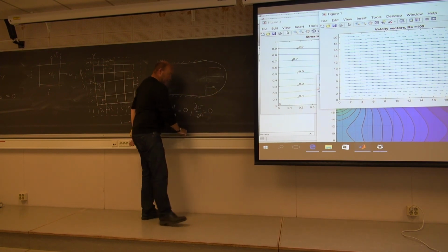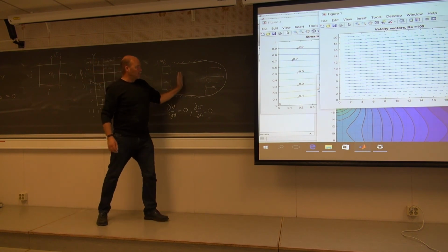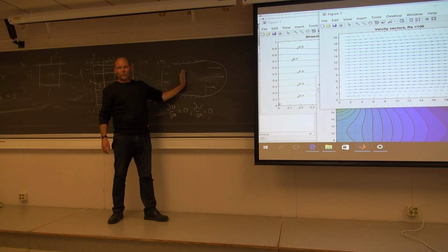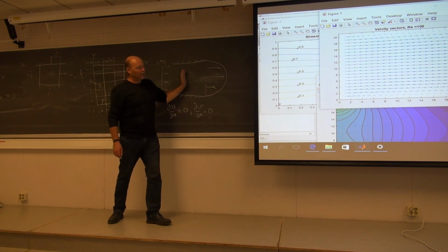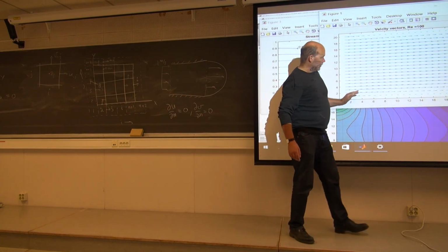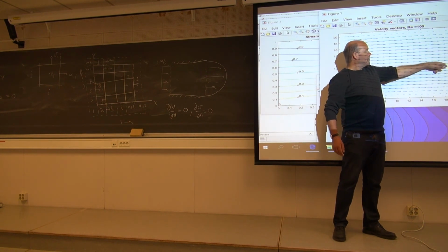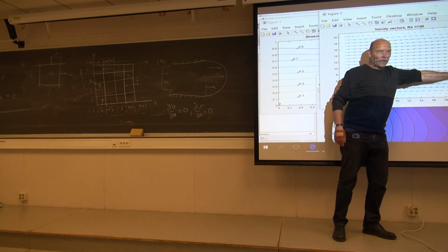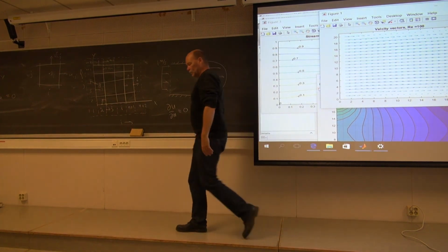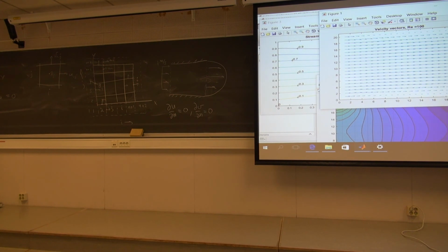And that means if you wanted this one to be fully developed, then you need a quite low Reynolds number. 100 is way too big. So it's not finished, it's not fully developed. You'll have a boundary layer growing here, but the boundary layer should grow so that they meet in the center before the outlet. This is not the case here, but that's part of exercise 1. Okay, that was the beginning, at least, for exercise 1.